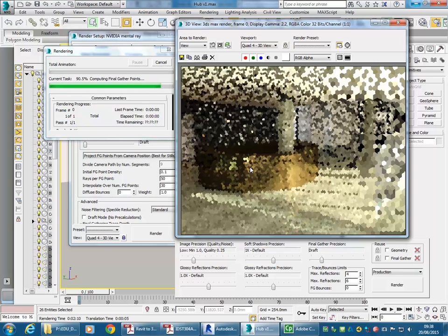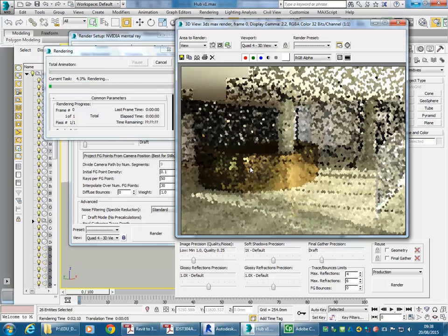Really the only option in Revit is to use artificial lights and increase the brightness by sometimes ridiculous amounts, 10 times, 20 times the original brightness. And then you've got to go back and set it to the original illumination level afterwards to get your nighttime renders to work. So that's a lot of work that you shouldn't have to do.